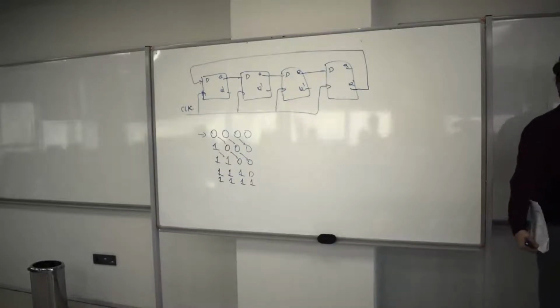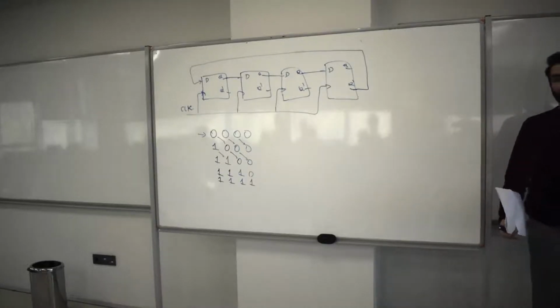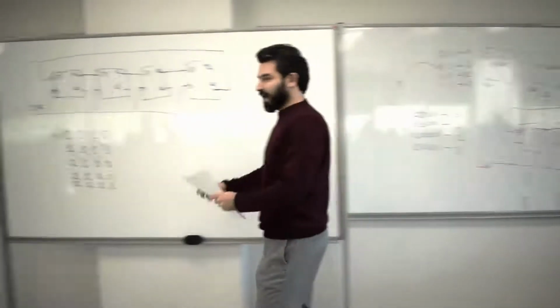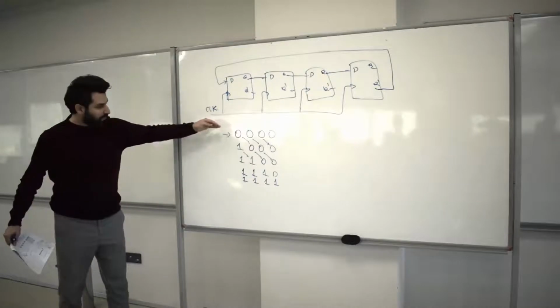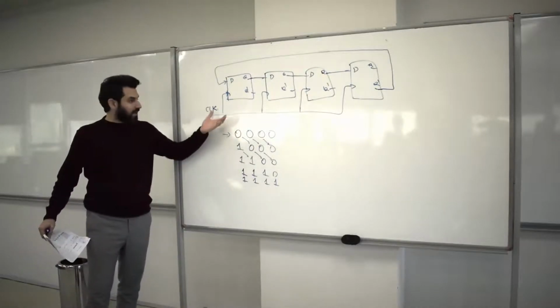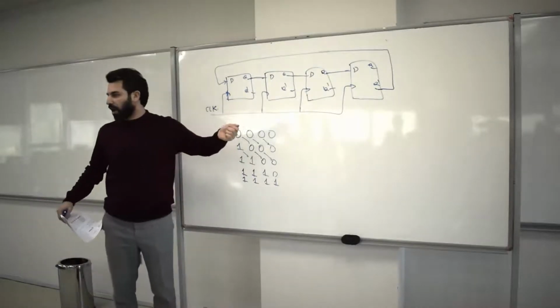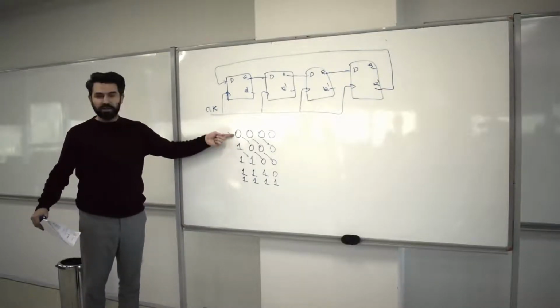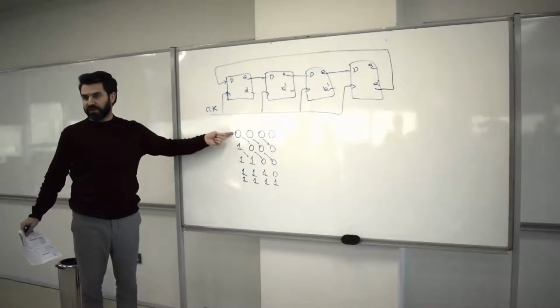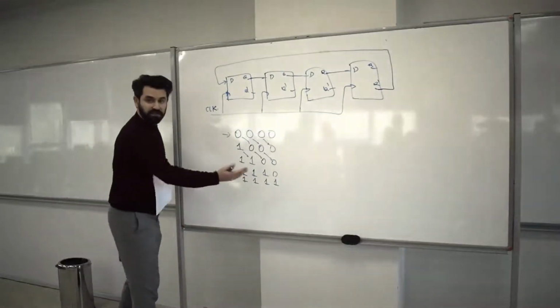And the period of that sequence generated is 4, because it generated 4 sequences. Okay? So now I'm doing the same thing. I'm applying exactly the same idea to the Johnson counter. Now I'm actually ticking the clock to see the sequences that are generated until I hit the one that was the initialization. Okay, that was the initialization sequence. So let me continue now.